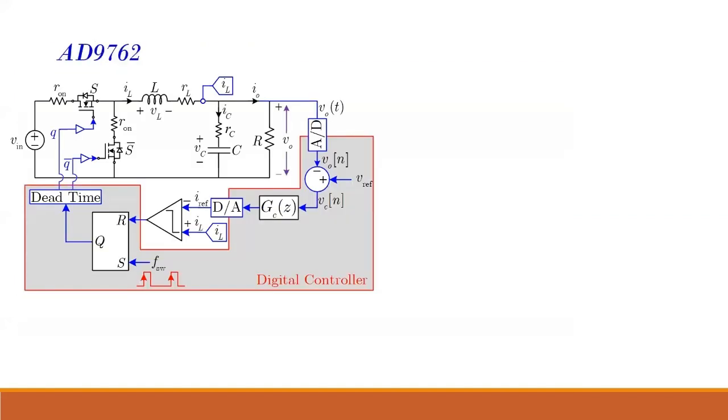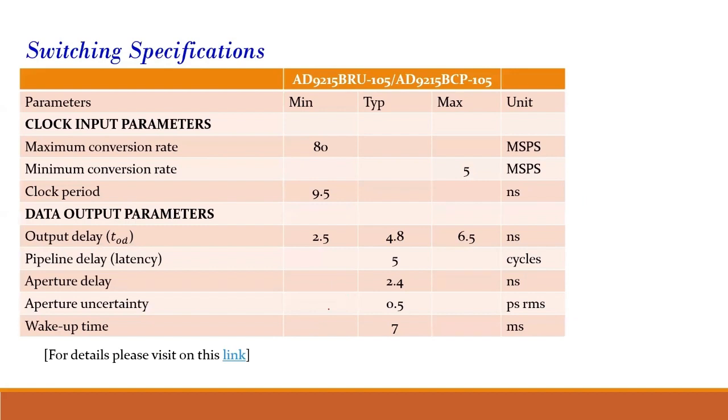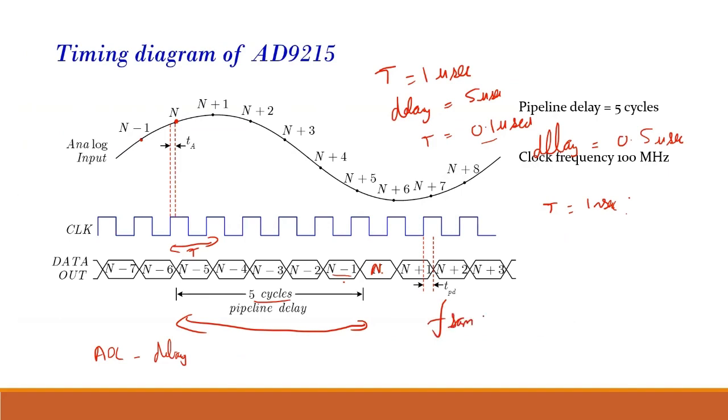Then there is a DAC. They have used a 12-bit DAC. Sir, the minimum T that we can use depends on the sampling rate, is it? Yeah. The sampling rate we cannot make very high. F sample is equal to 1 upon T. So we cannot make the sampling rate arbitrarily large just on our wish. It is constrained by the ADC specifications.